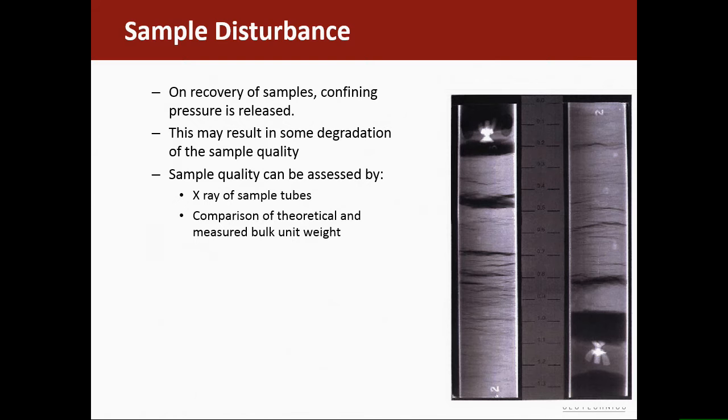Obviously, if you're going to do all this, you want good quality testing. You want to make sure they're going to be as reliable as possible. So the testing was actually done in Norway by the Norwegian Geotechnical Institute. But what they do is they take their sample cores along to the veterinary college, and they do a CAT scan of them. So you can see here the layering in the soil. Those are the end caps in the sample tube, and that actually is the sort of sample split, if you like, just to make it look better.